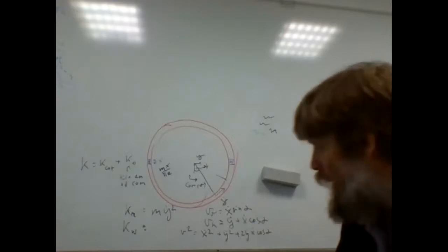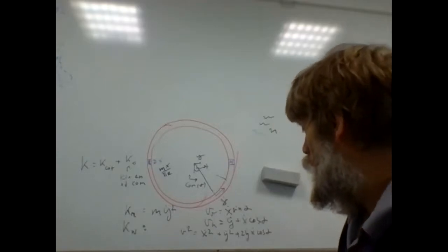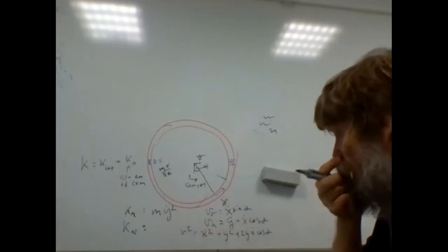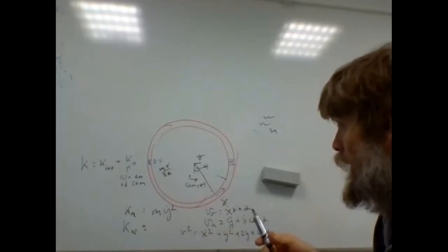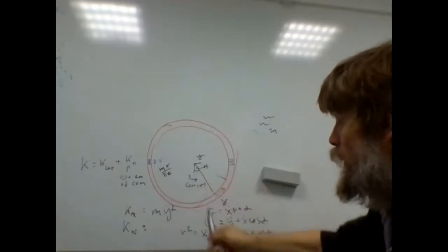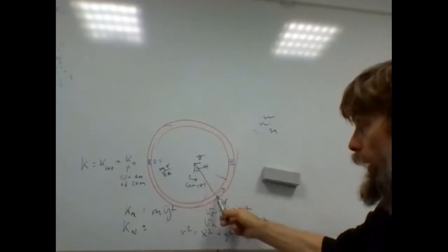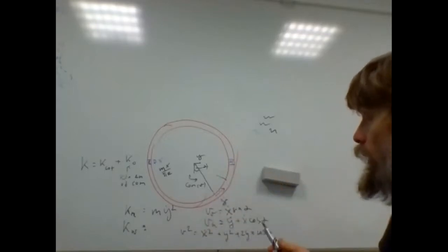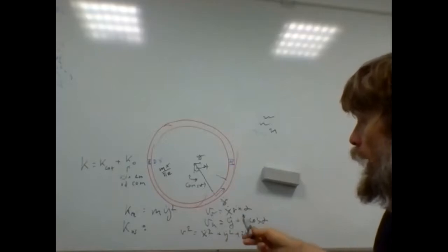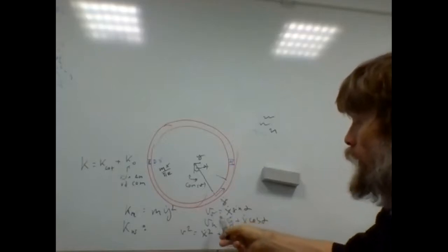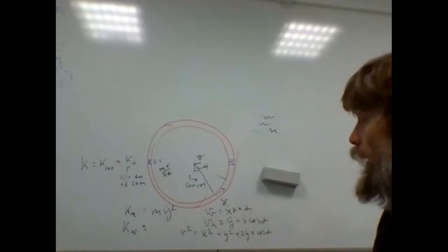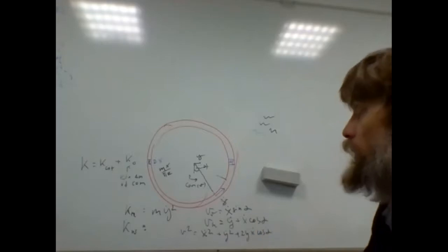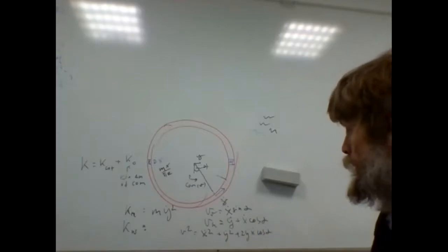And now we need to integrate. Can't we use superposition? Yes, this basically is superposition, addition of velocity. You add the velocity of the frame, which is y dot, to the velocity of the water parcel here, which is x dot in the tangent direction. So the vertical speed is x dot sine of alpha, and the horizontal is x dot cosine alpha. It's just a superposition, adding of velocity.